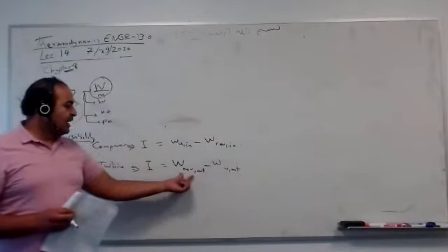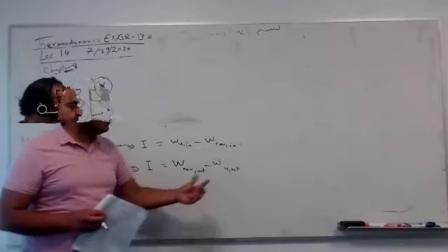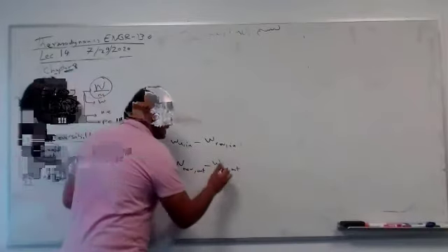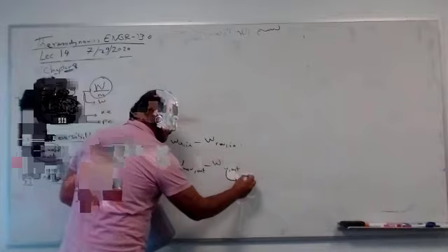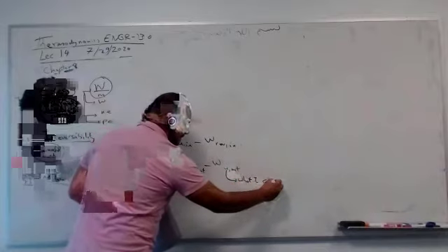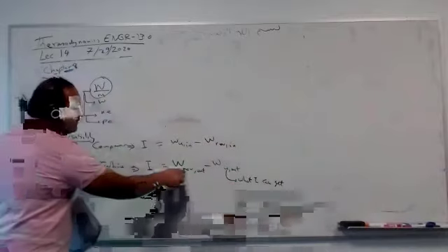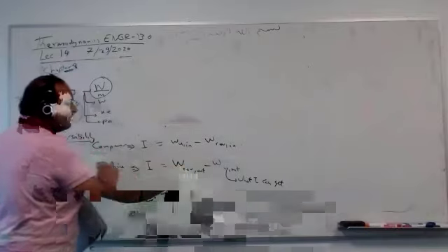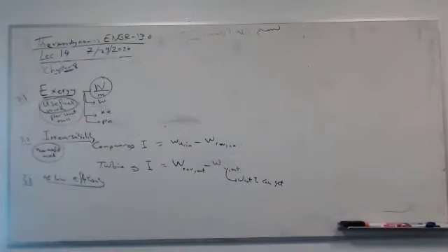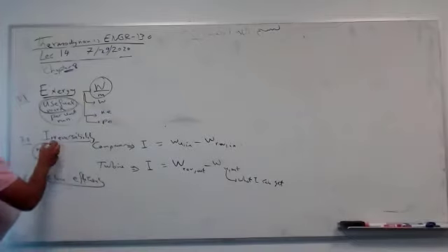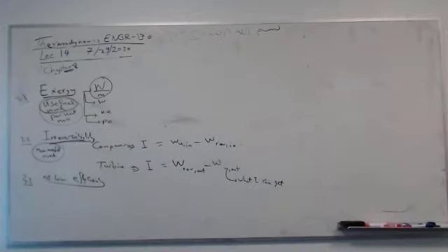So the reversible out minus useful, which is what I can get. It's actually lower than what I'm supposed to get if I'm reversible, if I'm ideal, if I'm Carnot. So the difference is irreversibility, how bad your system is. Exergy is useful. Irreversibility is non-useful, which is the difference.